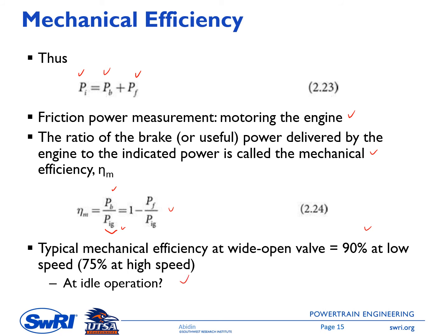And what will be the mechanical efficiency at idle operation? I think you can guess it. Okay, it is 0, because we don't have brake power at idle operation. You just turn on the engine and it rotates, the crank mechanism rotates, but it doesn't generate any brake power. Therefore, mechanical efficiency at idle operation is 0%.